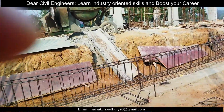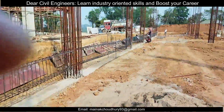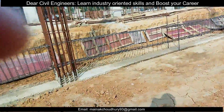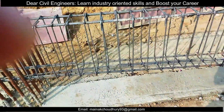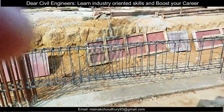So let's see one example. Here the rebar has started, so here there is no lapping. In the next span there will be lapping. So let's see the lapping zone which they have provided. Here, as you can see, there is a lapping in the bottom rebar. Here you can see the distance. You can see it by eye also.